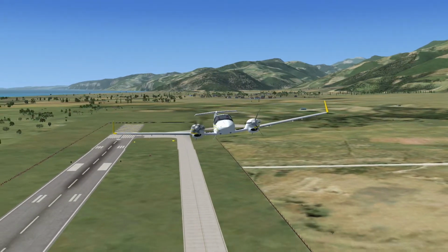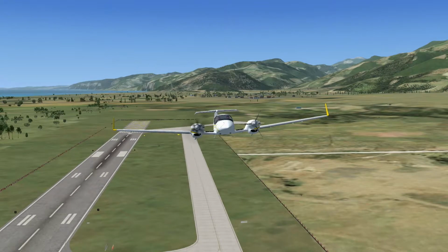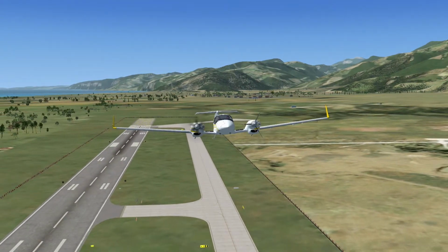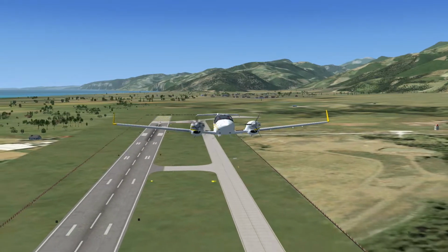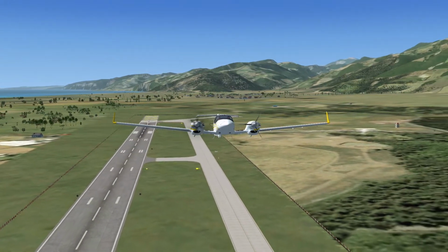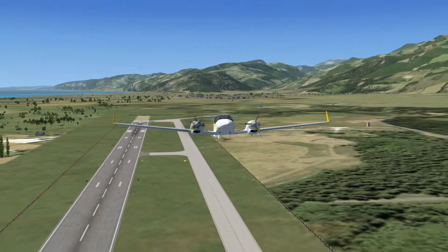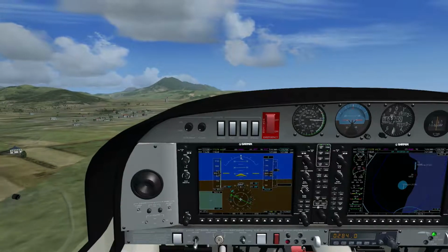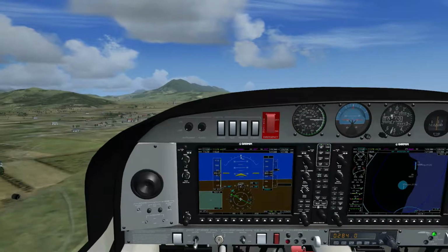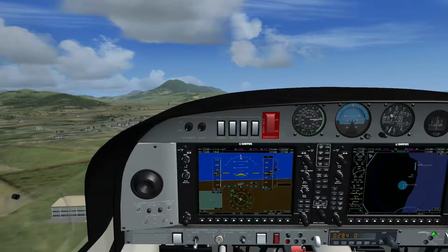Continue climb and pitch for 85 knots, VYSE. If the aircraft is able to climb and maintain good climbing performance at 85 knots, the student can select to use power to 92% as maximum continuous power.